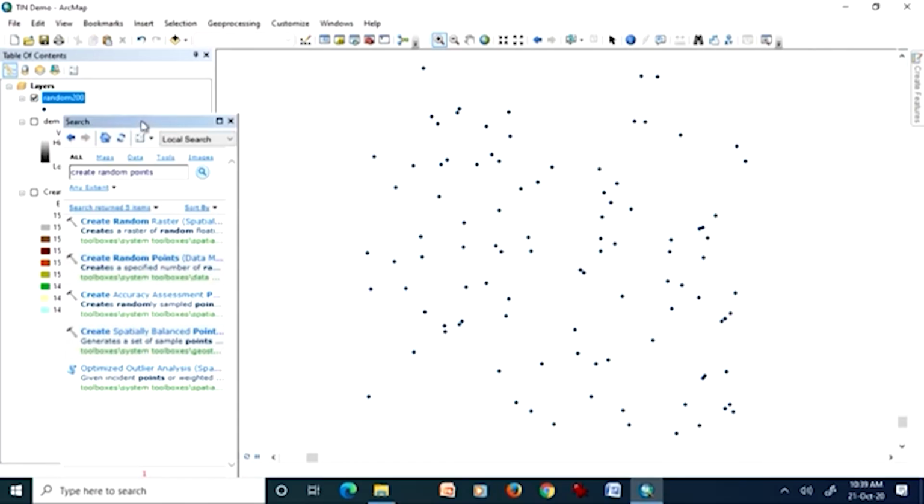So, why I wanted to show this is that you can select 10 random points or some random points. You can play with that. You can create random points, you can select random points, and you can use these random points to assess the quality of a digital elevation model, or even in that case a TIN. So, in that way you can assess how good it is on the border areas or margins, but generally you would find that in a TIN the margin issue might be there.